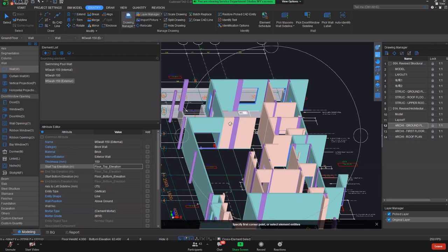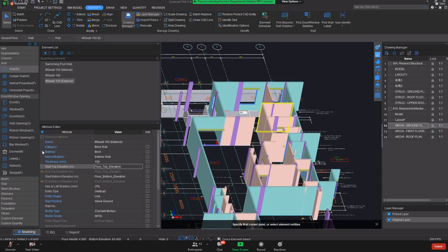The next thing is we identify the door and window schedule, and then we auto-identify it to the correct position. Last but not least, the lintel. We generate the lintel by auto-arrange. Auto-arrange means if there is any door and window, there will be a lintel preset.